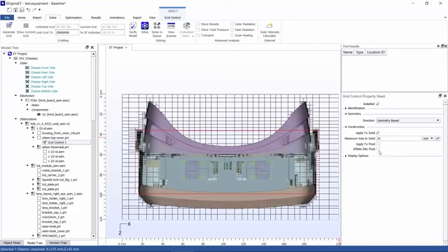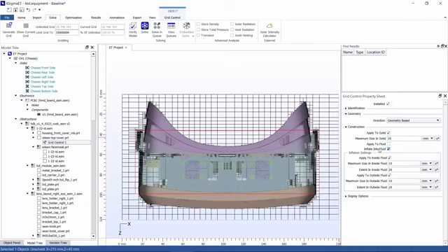And then finally, inflating the fluid will allow you to expand the grid from the surface of the object into the surrounding fluid. And so for something like this casing here, that would be what I would look at using. And so you have the option to apply it to the inside fluid or apply it to the outside fluid.